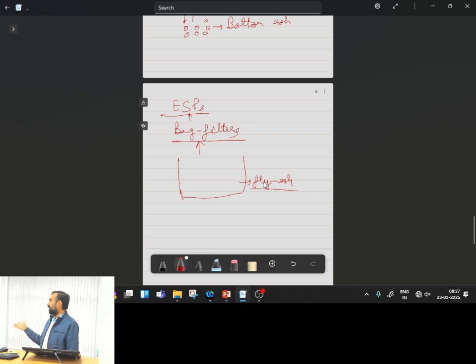Okay, and typically whatever Indian coal we have, it contains almost 40 to 50% of non-combustible matter. So it means that if you are burning a single train of coal in a day, then almost half of that will be actually in the form of ash, because half of that is containing the non-combustible matter.